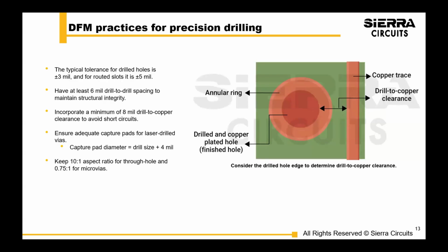Okay, so now let's talk about a little bit of drilling. So drilling is important, of course, for many reasons. One of them is you don't want any direct connect shorts, and you have to watch out for your drill to copper in that case. And a fabricator will typically increase your finished drill size on your drawing by 3 mils and plate down.